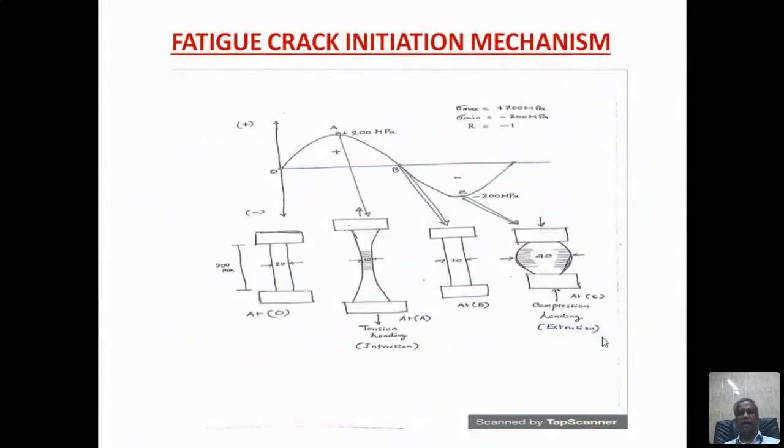So this is a small schematic diagram of how the fatigue crack will initiate. This is for one cycle. At the top is one stress cycle I have drawn. It's handwritten, and you see the stress cycle has a tensile stress field in the top half, and the bottom half is the compressive stress field. This is the specimen you are holding.